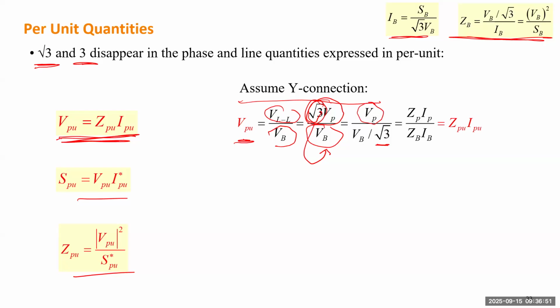The phase voltage is equal to the phase impedance multiplied by the phase current. And this denominator is basically just the base for one phase, which is equal to the product of the impedance and the current for the base value. Then for the last item, you immediately get per unit impedance and per unit current. So that's done. That proves this formula will always be true in a three-phase system.